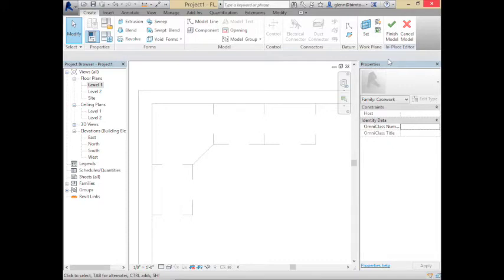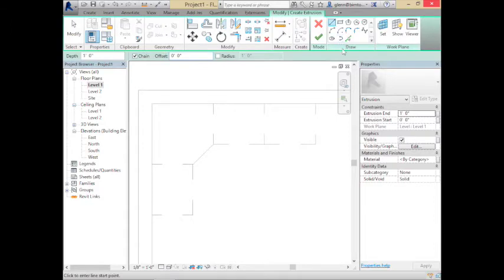And so we've opened it up. We're going to create the first piece that's going to fit inside the model. So we'll go for extrusion. We're going to start doing some tracing now. Now again, this is the point where you can draw if you like to. I tend to like to pick lines because then they line up very nicely. And I grab the little pick tool. So I'll pick the back wall here, and I'll pick the back wall here.